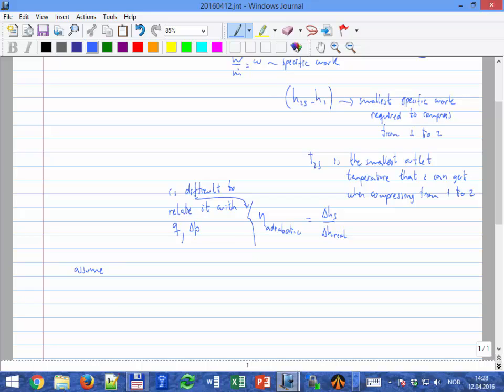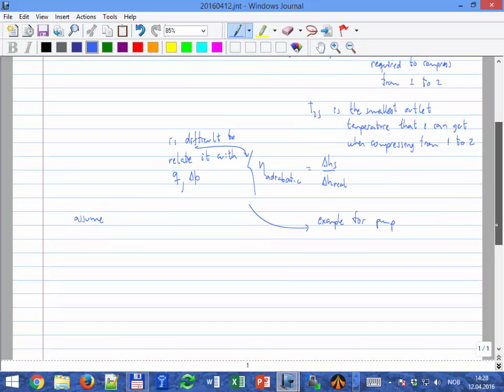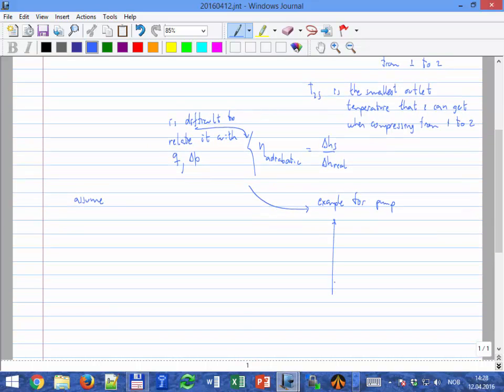It doesn't follow a trend, like in the case of the pump, I think I showed you, if you remember. Let's see here just an example for the pump. If you remember the efficiency of the pump versus the rate, it does something like that, because the blades are designed for a particular incidence angle.